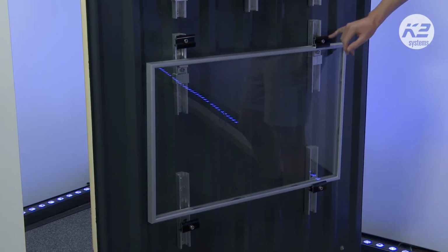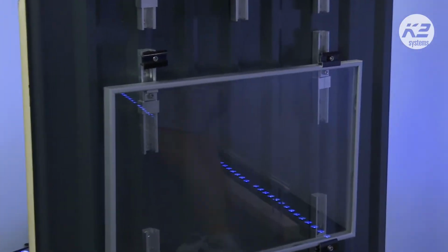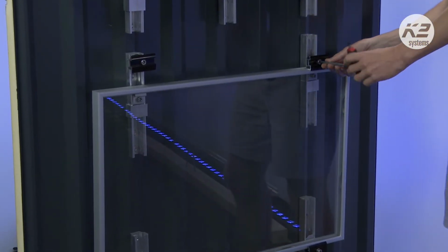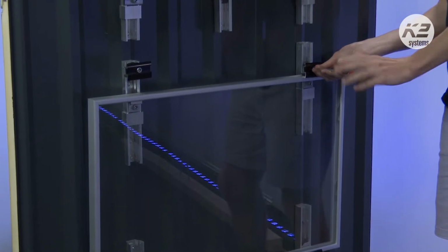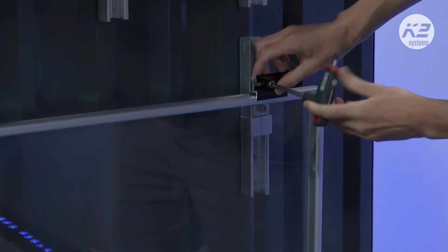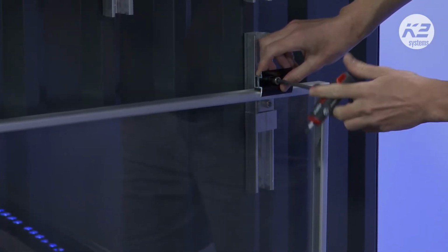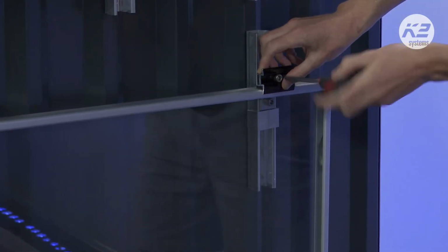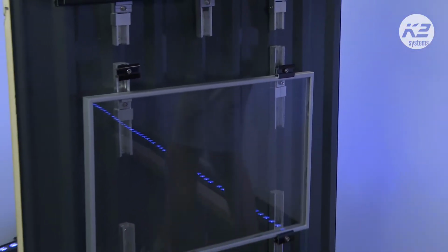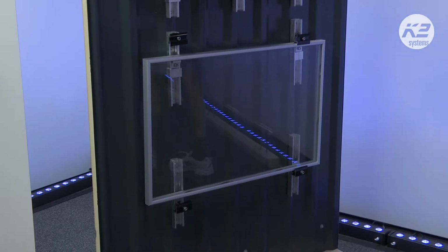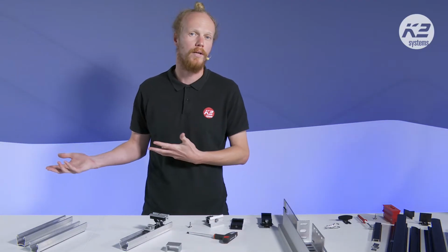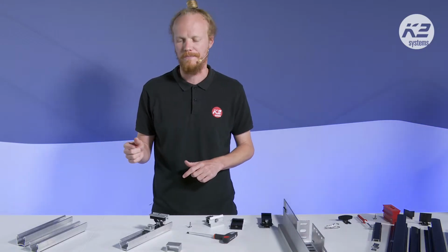So once we've installed the stoppers, we can then put the clamps in, and then we're just going to tighten. I'm not going to do them all, but just to give you an idea, sorry, I might need to loosen it first so I can lower it onto the roof, and then just tighten it into the wall. Right. So we do that with all our clamps, our mid clamps and our end clamps, and so it's effectively the trapezoidal MultiRail system with a slight addition.